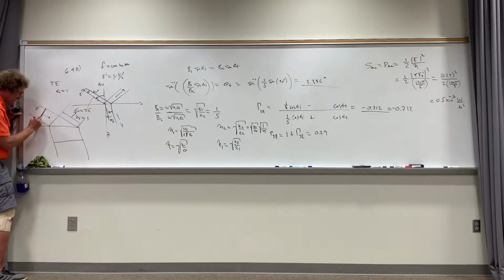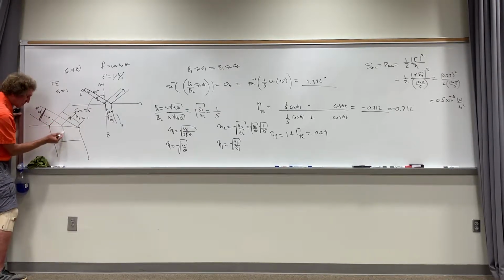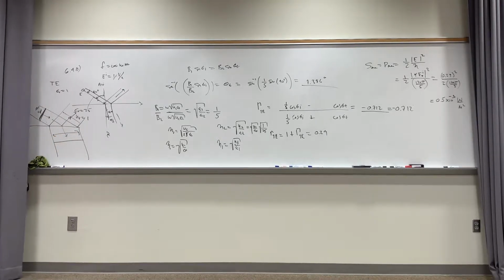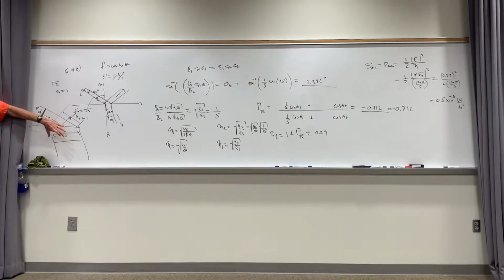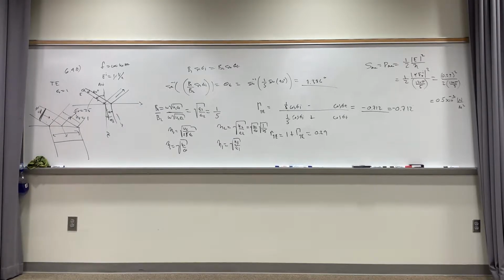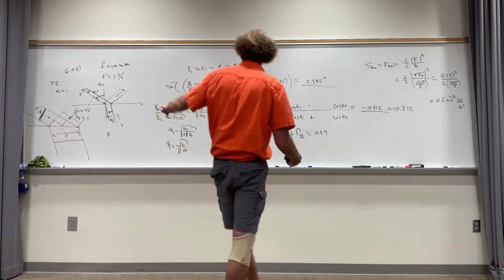But this power through here, the total power that penetrates this, give it some width D, and this some width D. This power will either be reflected that way or transmitted this way, but this is much wider than D. Do you follow me? And that's the way you get conservation of power. You literally have to build a little tube like that, and you'll see that within these tubes, the power is conserved. But the actual incident power density isn't equal to the reflected power density plus the transmitted power density. Remember that. That's very important. I'm just warning you about that because that's a common flaw with these tubes. I don't usually cover that.